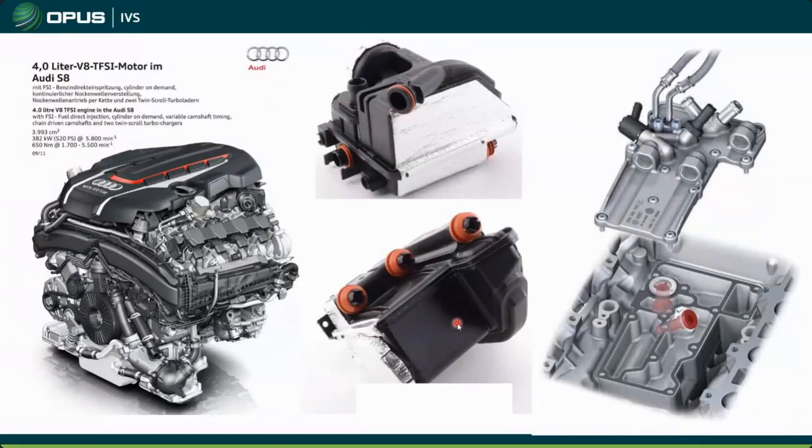And these use a very similar system for crankcase ventilation. You have your pressure regulator / oil separator, and then in the V here underneath your turbos. So of course, because it's impossible to get to, it's going to fail. And then you have this plate in the actual V of the engine, where your valve plugs into for the various breather systems, right? Whether you're under boost or vacuum, obviously that's going to vent in a different place.